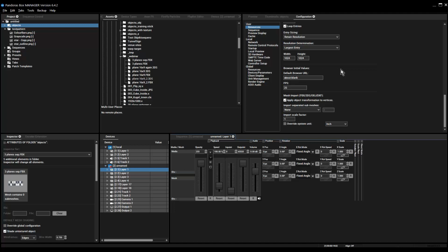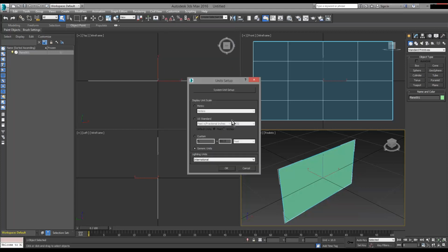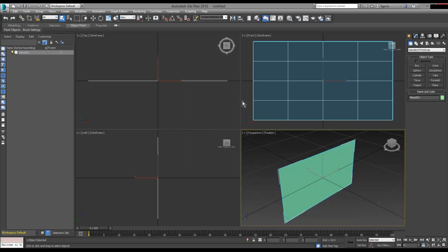Can we do scaling during export? I tried to find out how to do this correctly in 3ds Max, but I couldn't. Even when I tested yesterday and set the unit setup to inch right away, it didn't make any difference, which I thought was a little weird. And when I export it, I don't have any export dialog for 3ds. For FBX, I do have a lot of settings that I can choose, but for 3ds, it's just doing one thing and I cannot really influence it.